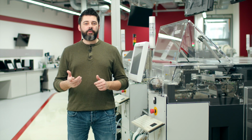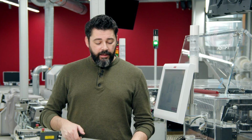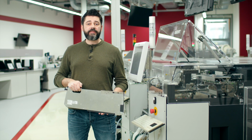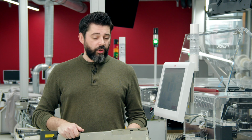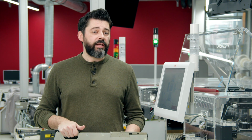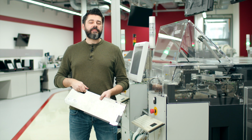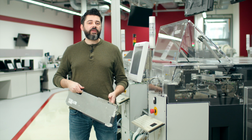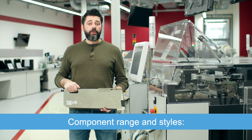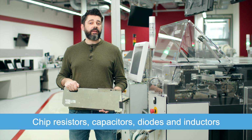So here we are with the item of interest, our SIPLACE Measuring Feeder X. The feeder is an on-demand device to detect components and the component range. What can we do with the feeder? We can detect splicing issues, we can detect labeling issues or setup issues. And last but not least, of course, we can detect customer deviations if you have, for instance, fake components. What is the range of it? We can measure resistors, capacitors, we can measure diodes and inductors.